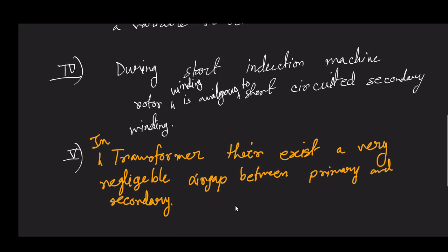If you watch a transformer construction video, you will find that generally the low voltage winding is wound on the limb of the transformer, because the limb or the core is going to be earthed, so that will always be at earth potential, and the low voltage winding is placed adjacent to our core, and on that low voltage winding we place our high voltage winding, but there is a very thin gap, and sometimes this is filled with air and sometimes it is filled with other materials.